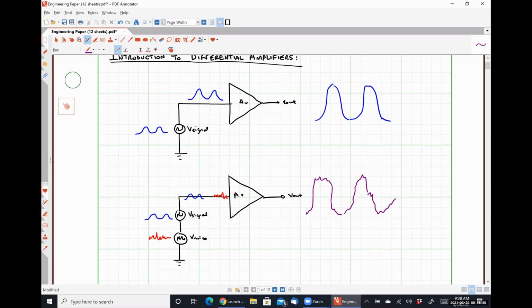In a circuits-based approach, we're really kind of limited. Those are still the three different ways that we can do things, but we often see that we have limitations or constraints. So for instance, if we wanted to decrease the coupling, which is probably the most obvious thing, we might have to move different portions of our circuit physically away from each other, which is going to increase their size, increase their footprint, and increase the overall chip cost and things like that. So while that's probably the best way to do it, it's also usually the most expensive way.